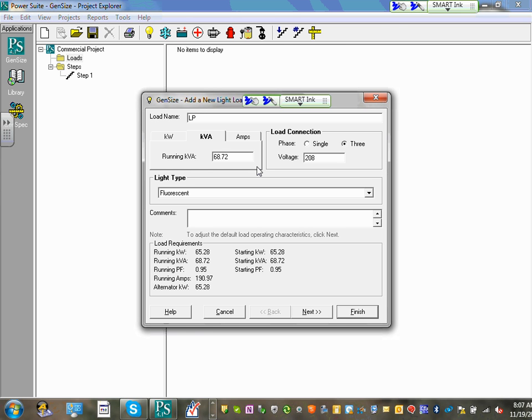You would have realized that, guys, because when you get up there, it will tell you there's no big generator that can handle it. So you say, "Wow, that's a small load." So you would have realized that if you made that mistake. Common mistake. Okay, so here's my KVA. Look at this. What's the voltage? It's 208. It's 3-phase. Now I know the lights are single phase, but the panel that feeds the lights is 3-phase. So it will all be seen, Adam, as a big chunk of 3-phase lighting load. Cool? Right underneath it, what type of light are we using? We're using incandescent, discharge, fluorescent.